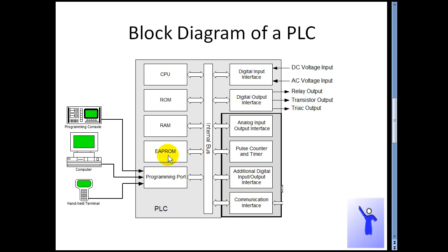And this is EEPROM, which is almost nothing other than EEPROM nowadays. It is just electronically alterable programmable read-only memory or electronically erasable programmable read-only memory. This EEPROM is used to store user data that must not be lost when the power is turned off. Values of timers that must not be lost. It can contain configuration variables. It can contain any data that the program specifically specifies that it must be saved even when the PLC is